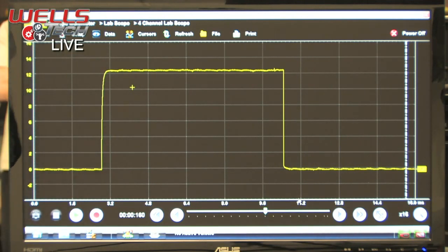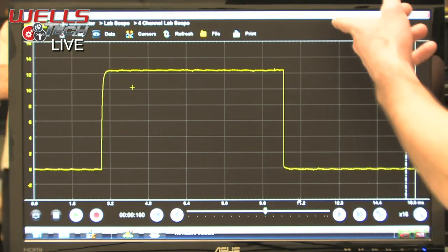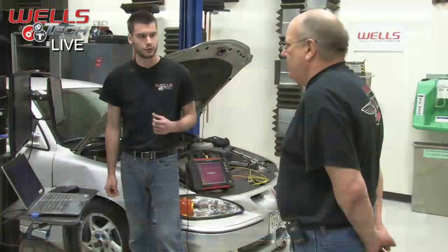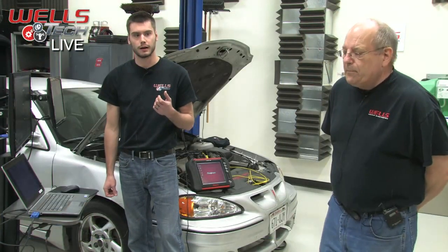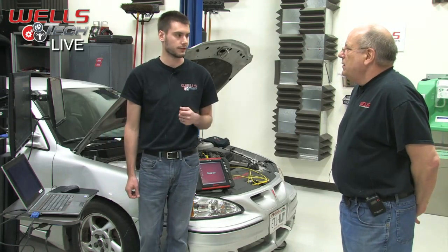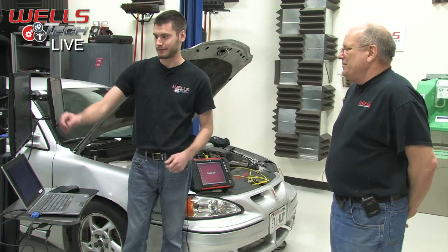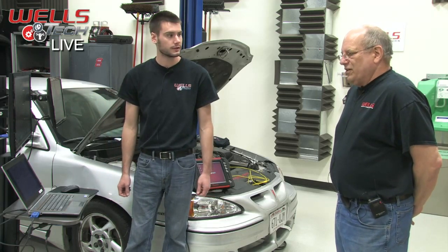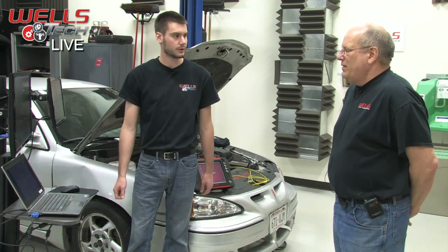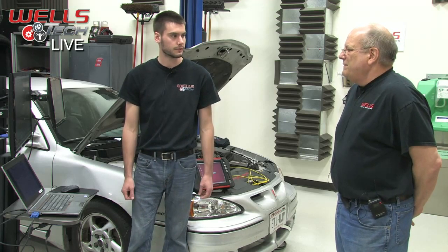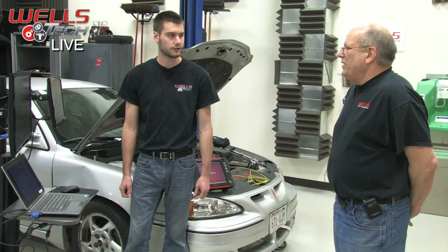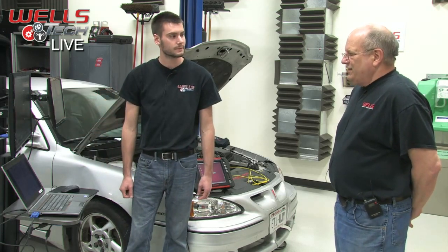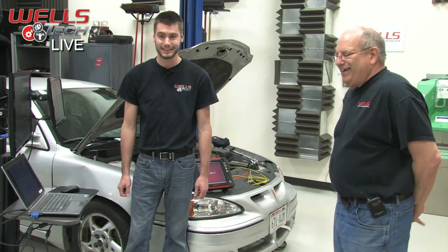Absolutely. And with the hash marks here, we ran into this a few weeks ago. We were using a different power supply for the scope, just a two-wire power supply without that third ground terminal on it. And we were getting almost half a volt of hash here just as interference in the scope. That's a good tip. So we changed the power supply to the grounded style three-pin connector into the wall, and it went away. Now we have almost zero interference. So a 60 cycle hum. Yeah, you've got to watch out for that.